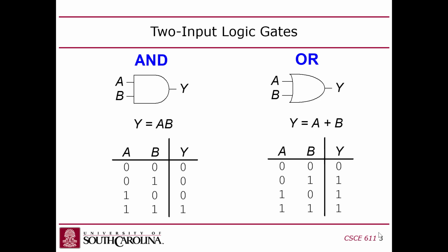Now, usually when you see a logic gate, you think of that being built with transistors on an ASIC, on a semiconductor chip. But I mentioned last time that on an FPGA, these gates are built using LUTs, lookup tables. On an FPGA, these lookup tables are actually created in a 1-bit wide RAM.